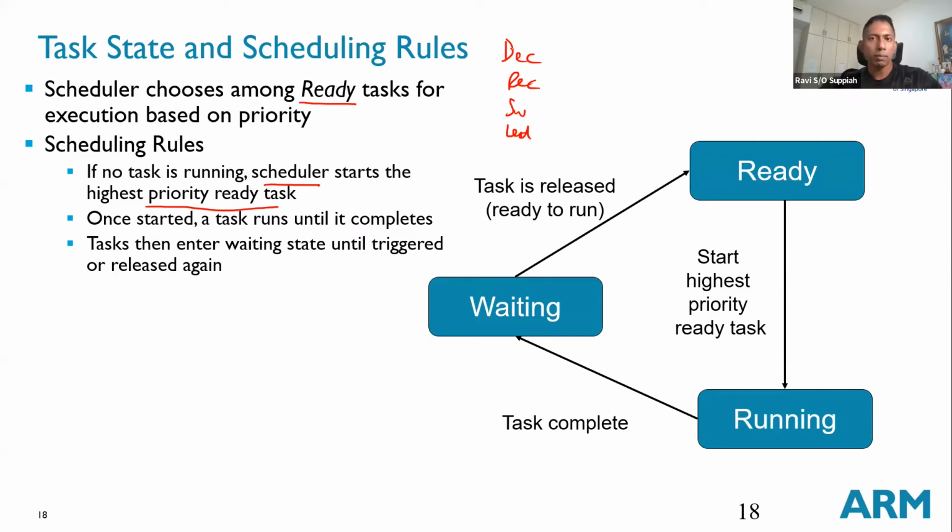Now of course in our system maybe we say that decode is the highest priority. But decode may not necessarily be ready until new data has been detected by the GPS module. If there is no new data, then I can just follow through the sequence. Maybe you have programmed it such that incoming GPS data triggers an interrupt, and from there I can set a flag to know that the new data is ready. If the decode task does not need to run now, then I may run the other tasks in sequence. But the moment the decode is ready, I will have to transition it to the running state. All the tasks are in a waiting state, and the scheduler will select one of them to go from waiting to ready, and of those in the ready state, one will go to run.